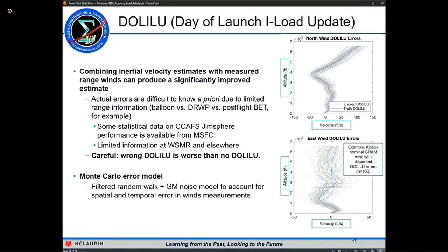you can take an extra time derivative and come up with an alpha dot term, and this falls out of a technique that's used for tail-controlled missiles for doing normal acceleration control. We just back up a step and use it with the gravity turn assumptions to come up with a control law that does alpha control, or alpha regulation. What we end up with is a guidance law that we can wrap around the inner loop that uses rate command feedback and knowledge of acceleration and the alpha to provide a PI-like response that's very well damped and relatively high performance and really just doesn't perturb the inner loop at all.